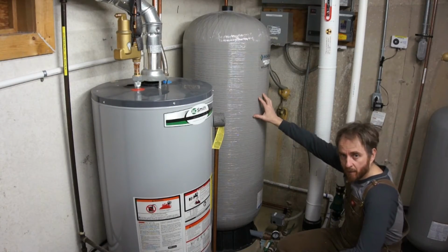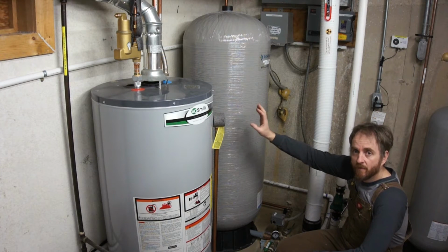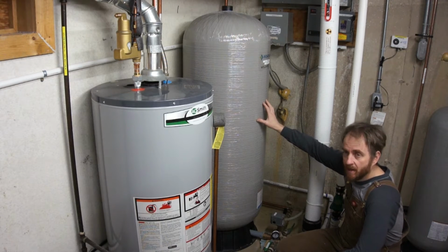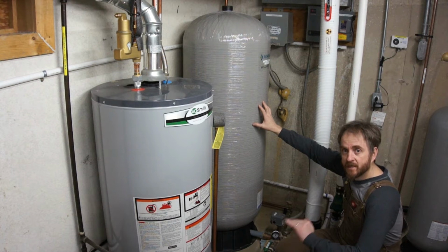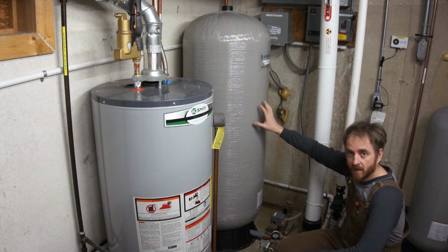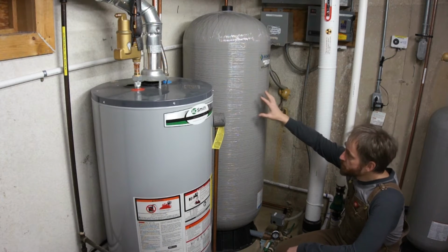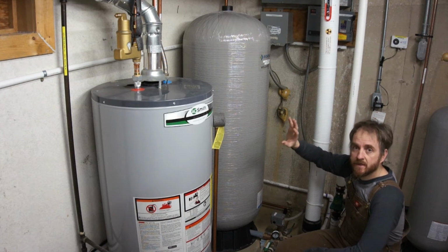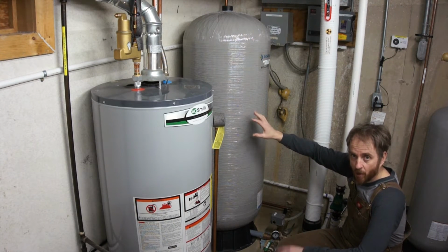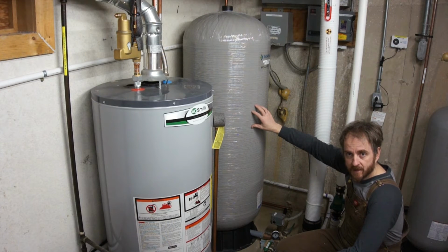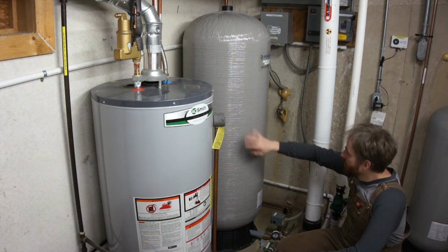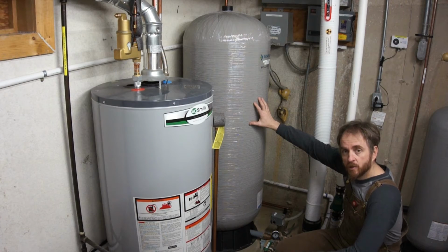This is a 60-gallon pressure tank. Water is pumped from the well into this tank. What this does is it provides constant pressure to the house. This one operates between 40 and 60 psi. So once water is pumped into here, it supplies a constant water pressure between 40 and 60 psi. The water in this tank is still untreated, raw well water.